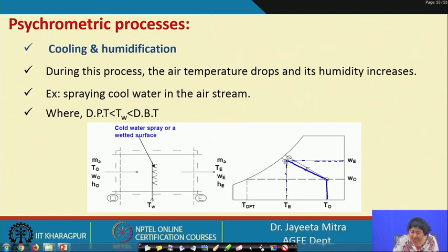If not fully saturated, an increase of the RH may happen. Corresponding to whatever moisture has been added to it, we will calculate the exit temperature, that is, the dry bulb temperature now. If we want to know the difference in the enthalpy, we take the difference between the first point and the second point.